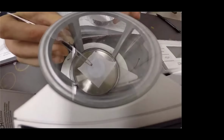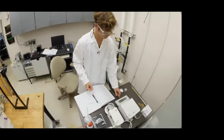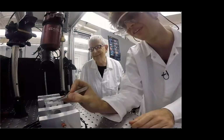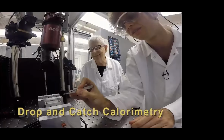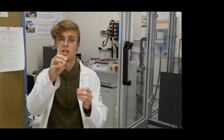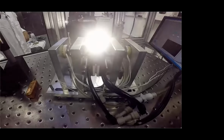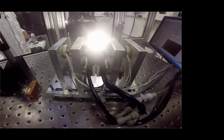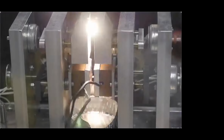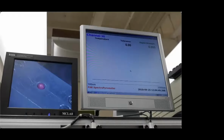You try to make a sample such that it's not in contact with anything other than the inert atmosphere. How do you do that? You levitate a sample. The technique is called drop and catch calorimetry. They levitate a bead, zap it with a laser to melt it, and then drop it. And so what happens is that the bead is heated up here and it falls, and then we just, like that. As the bead solidifies, sensors behind those copper plates measure heat flow and a property called heat of fusion, how much energy it takes to melt the material.